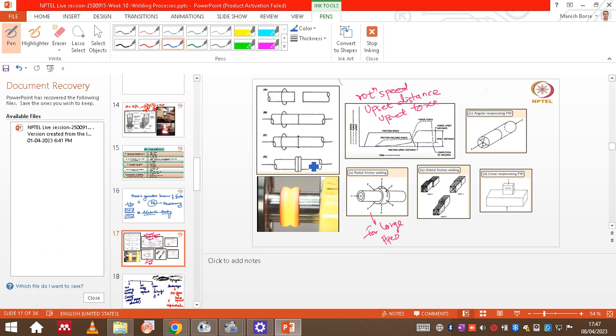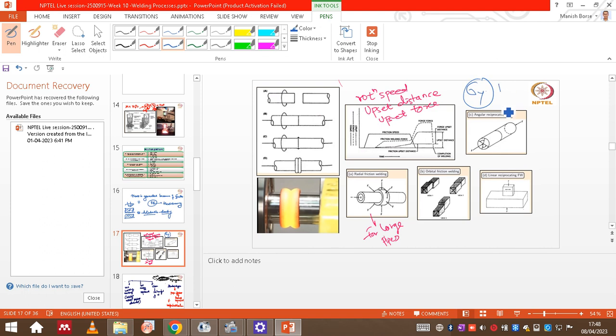So let's say in friction welding, one component is stationary and another component is rotating, and because of that friction will be generated at the interfaces by giving a certain upsetting force at the start of the process, right? And once the friction and heat generation are sufficient, the sigma y of the material will decrease and the material will come into the semi solid state.